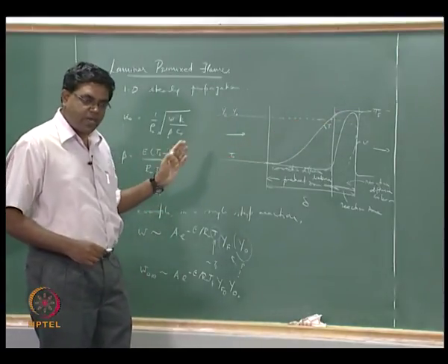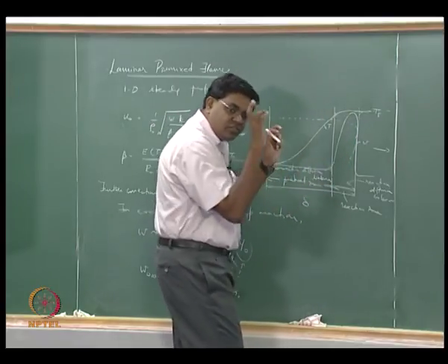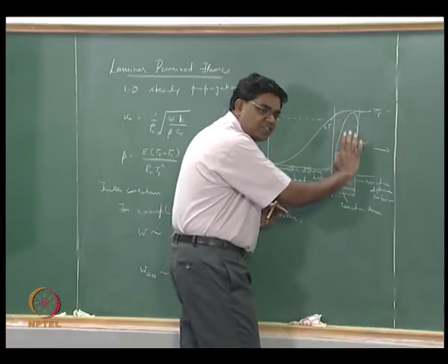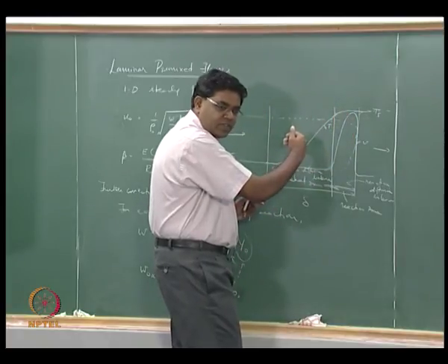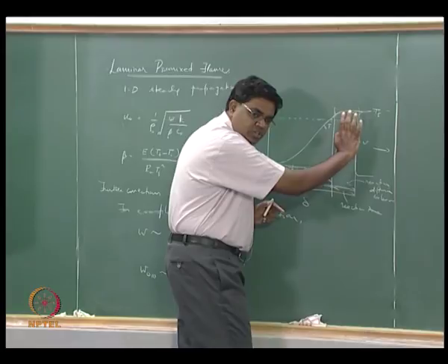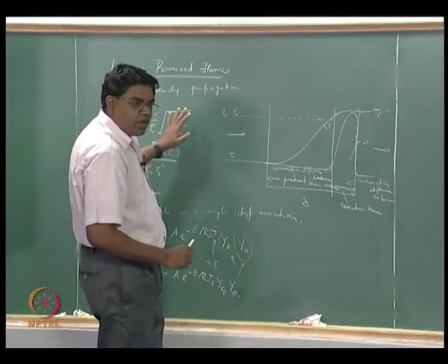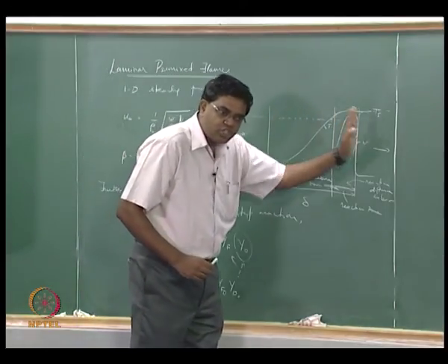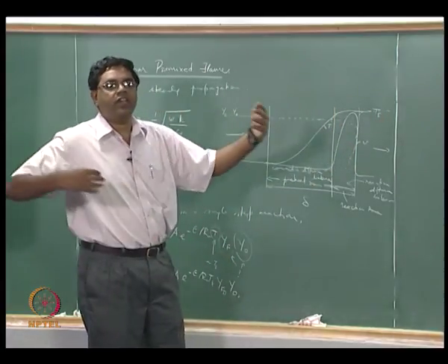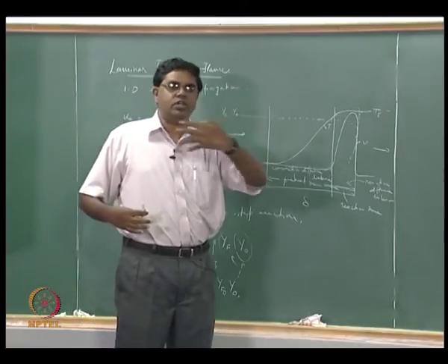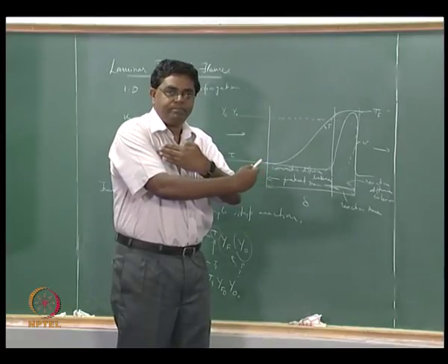So effectively we should now begin to expect a product concentration profile that is similar to the temperature profile itself, because the way it happened was you now had a lot of temperature here that was produced, quote unquote temperature being produced, that is essentially heat is being produced, so the temperature is locally getting raised and then it gets conducted. That is not very different from species mass getting produced and getting diffused upstream, right. Even in the case of energy balance, you had an enthalpy flux that was trying to wash this hot region away from here, and this heat conduction was like a convective diffusive balance. It is trying to conduct heat upstream despite the flow wanting to go downstream, right.